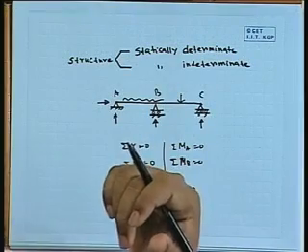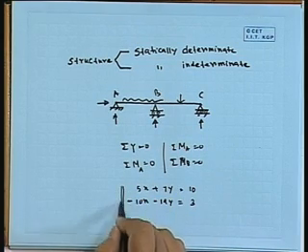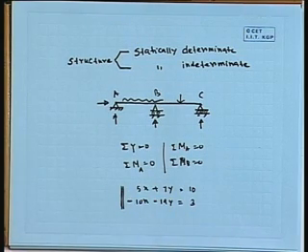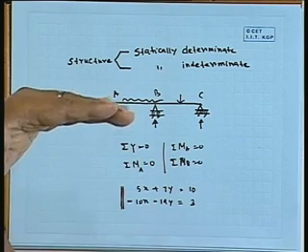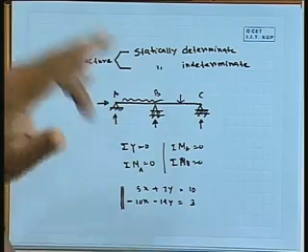So, there can be a tendency initially that we can take moment at any number of points, generate any number of equations, and solve any number of unknowns, but if you make an attempt, we will more or less get that type of equations. So we will basically get 2 independent equations here, apart from the horizontal summation of the force.